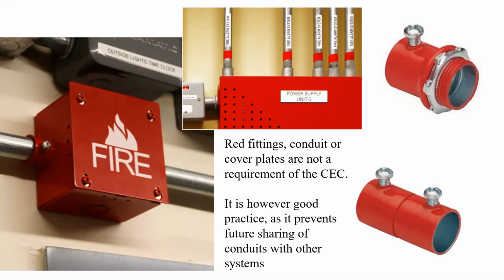Some of you will be used to seeing red fittings, red conduit, or red painted cover plates. This is not a requirement by the CEC. However, it is good practice as it prevents future sharing of conduits as installations and alterations take place through the lifetime of the installation.